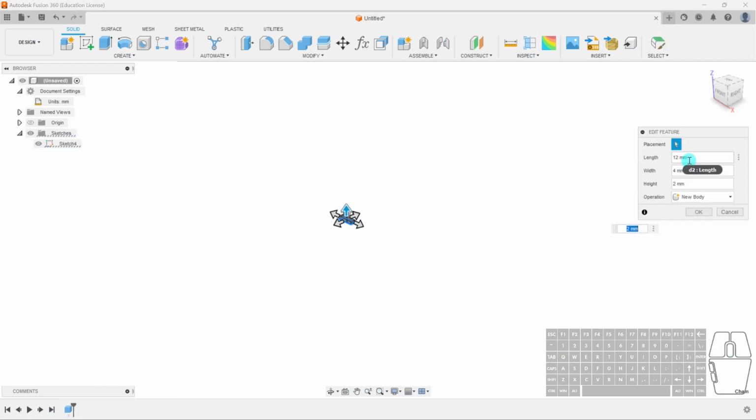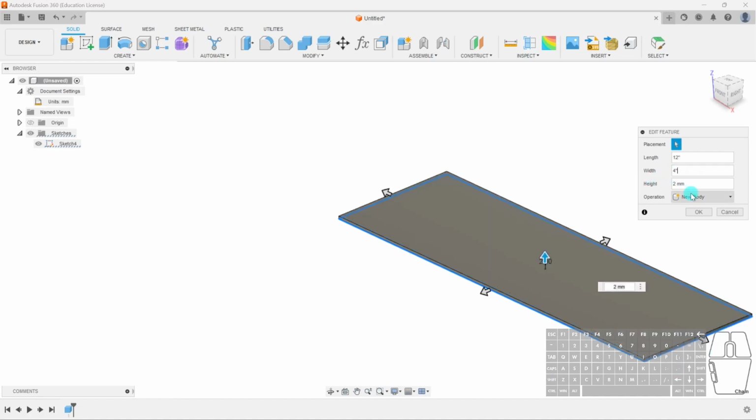But what can I do? Well, the trick's in here. You see this millimeter thing? Remove that and put in a double quotation mark. And that basically is the symbol for inches. So now if we do this for the rest, inches,